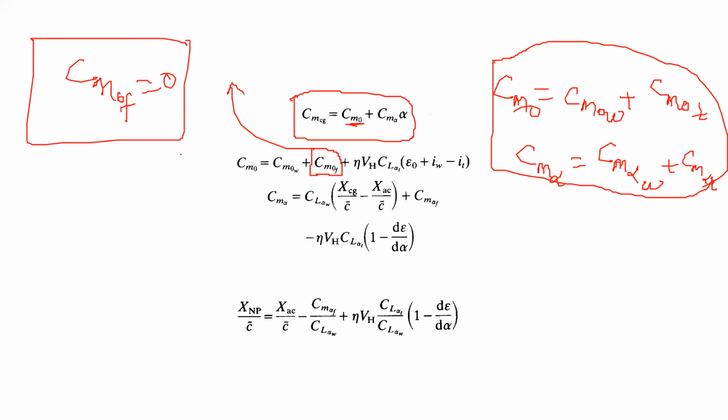But if you want precise calculations, you need some idea about the geometry of the fuselage and the weight distribution, because it entirely depends on how the weight is distributed, right? And the geometry of the fuselage. So it depends on both, right? By knowing the geometry, you can compute the effect from the fuselage. There are methods given, but for simplicity, you can ignore it in very basic analysis.